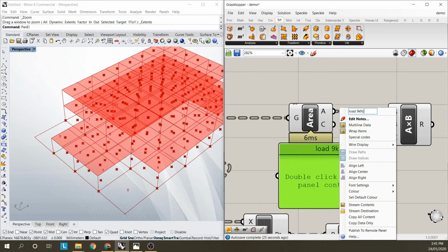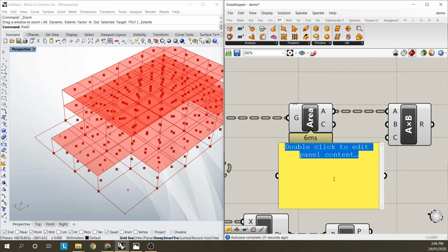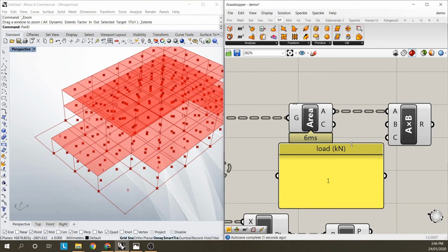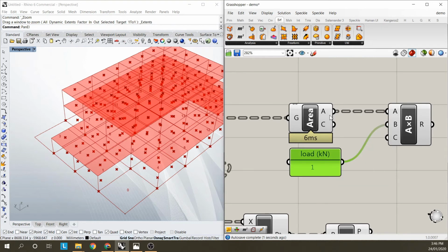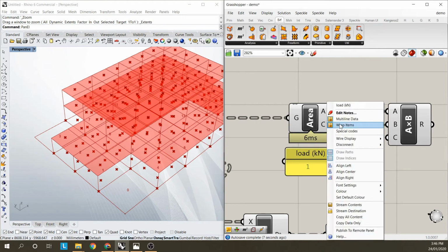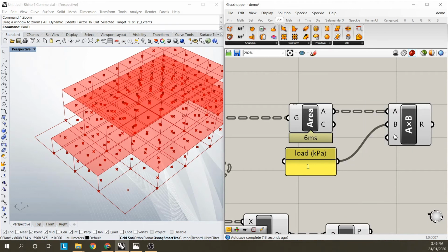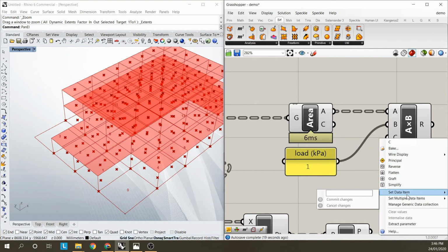And I'll say just 1 kPa for the moment. It's going to be a lot more than that. But if it's 1, you can see the results pretty quickly. So the area times your load of 1, I said kilonewton, I meant to be kPa. 1 kPa, and then I'm going to multiply it, because it'll be in millimeters, by 0.001231.